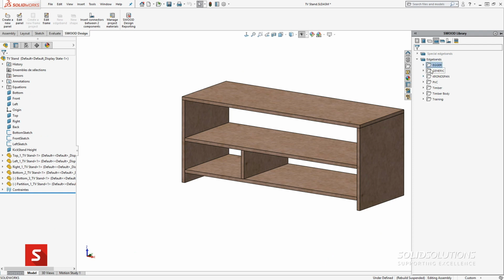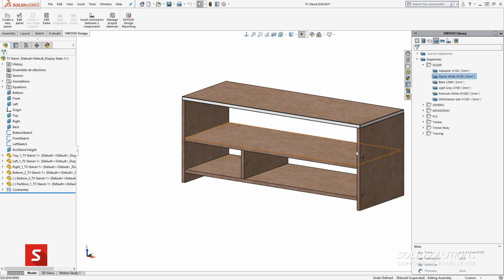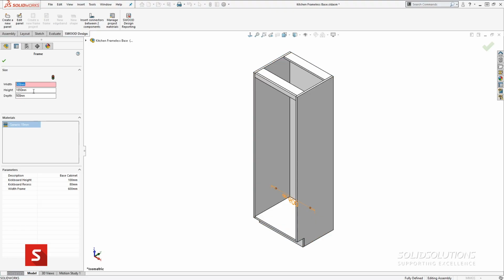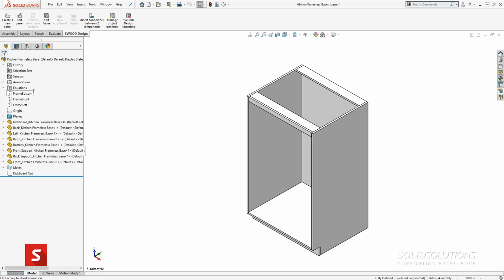Examples of this would be edge bands. You can actually apply edge bands within the model, decide what edge they're being added to, and also what order they're being added in. That can be easily communicated down to the shop floor. Other information such as materials, grain direction, hardware such as cams, fixings, dowels, screws, Clamex and the like as well, but added in a much more efficient way than is commonly done through SOLIDWORKS or other CAD platforms.